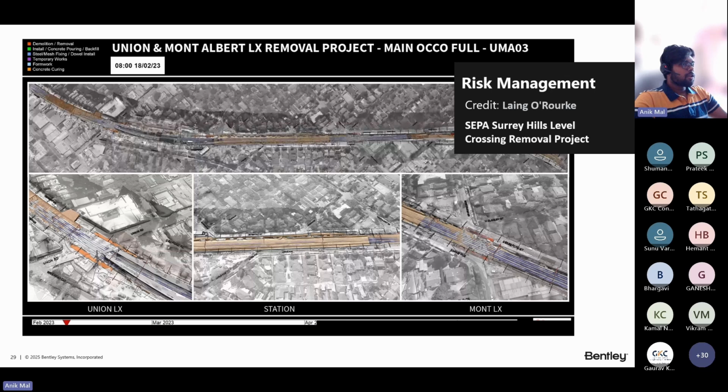90% of the major lifts were sequenced using the Synchro 4D Pro simulation tool. Traditionally, this used to be planned using static 2D CAD drawings in isolated files. There was no scope to take into consideration the various interface work that was happening simultaneously. Compared with the traditional method of interface checking, the Synchro model reduced the risk of clashes by 75% in the potential work, providing them greater visibility.